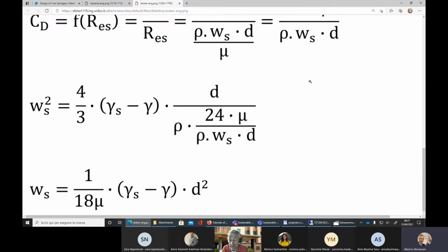Sediment size is driven by downstream requirements related to water use. For instance, if water is used to produce hydropower, then there is a limiting sediment size, which is given by the manufacturer of the turbine that you use to make the power.